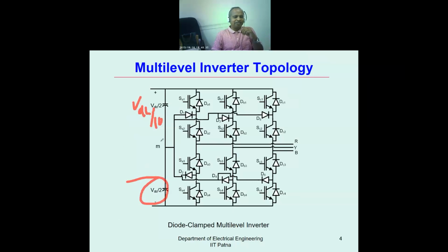It may charge like this because the internal resistance, or ESR, of the capacitor is unknown to us. In simulation you will never get this unbalance, because simulation is always perfect.